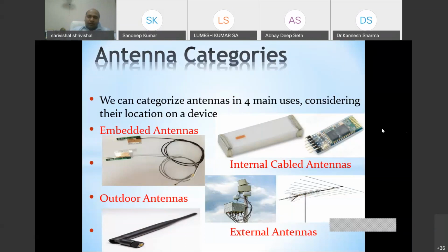When we were talking about the embedded antenna systems, these are already integrated in the part. They are part of the design, like RFIC antenna systems. These antennas are directly integrated with the IC part, so you cannot remove them. As well as their feeding is also through the board. If you look at the board, you can see there are some connections taking out. So these are working antenna systems, and the feeding part is also managed through that IC or through that PCB board itself.